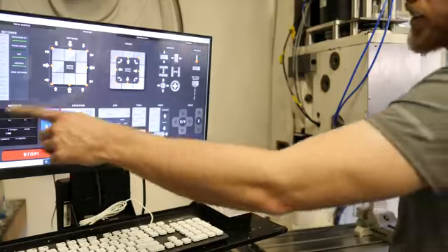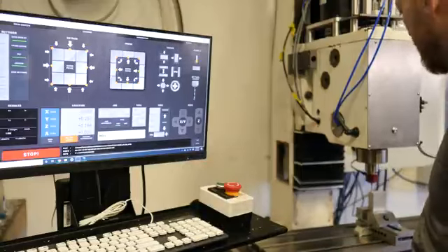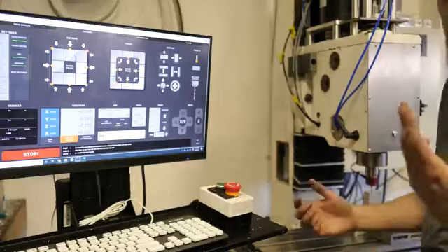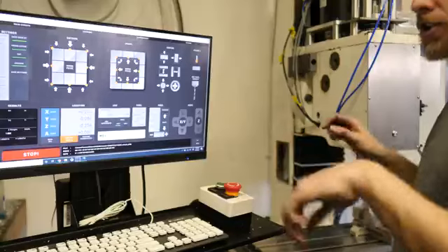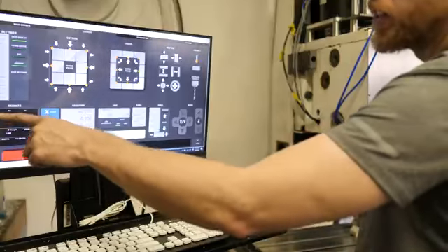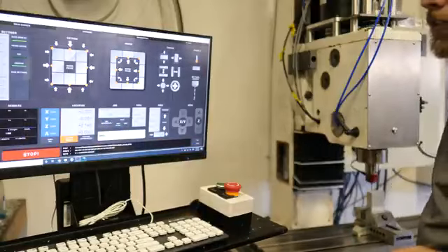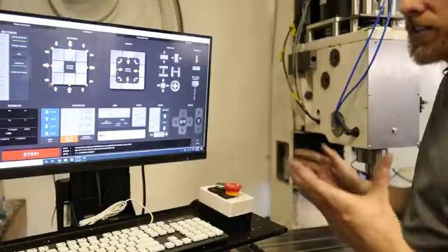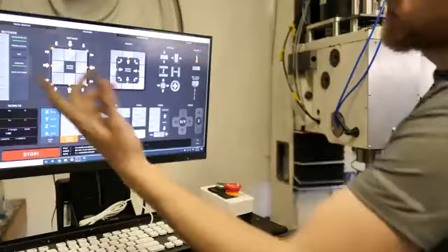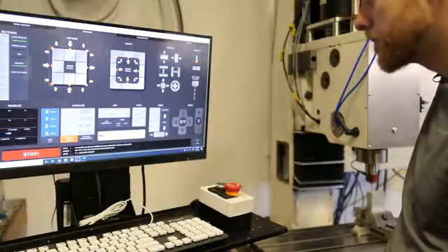This results page is actually super helpful for doing your calibration of your probe tip as well. Like I put a workpiece in here of an exact known dimension, in this case a 1, 2, 3 block, and I measured each side of the 1, 2, 3 block, and it'll tell me the X plus, X minus, and the delta between the two. So if it says exactly 3 inches, then I've got the probe tip right, and I calibrated it that way. You see here now we're within 1 thou. Pretty accurate enough for the stuff that I do.